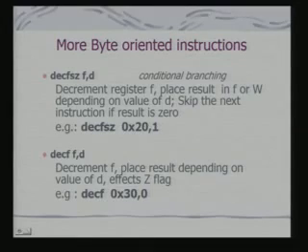What is the motivation for designing such instructions? Because similar instructions you will find in other microcontrollers and processors targeted for embedded systems. This increases what we call code density. That is, instead of using 2 instructions, that is one instruction to decrement and then jump, you are using a single instruction. So the number of memory locations that your code would occupy can decrease. If it decreases, what does that mean? You require less memory, and obviously when you are working in an embedded system, you try to work with less memory, and less memory would also imply less power consumption.